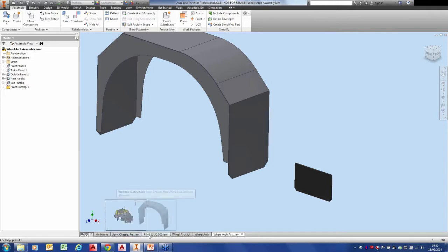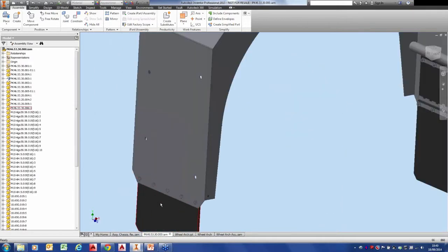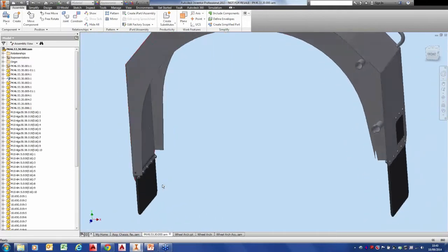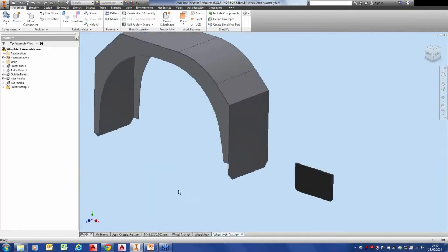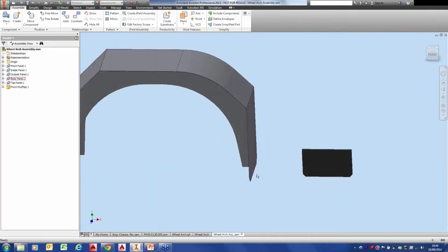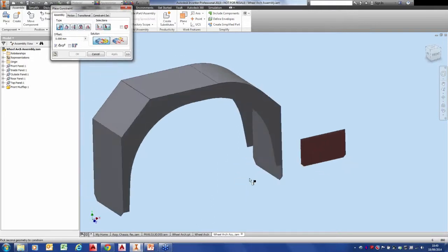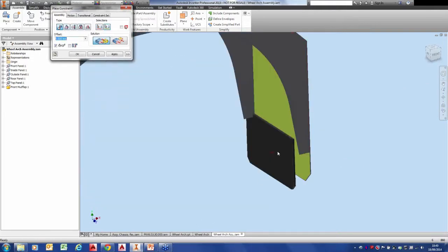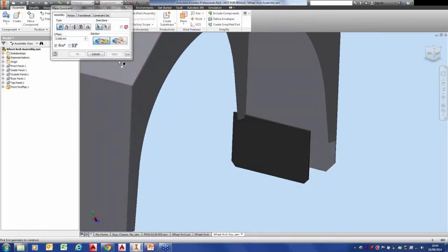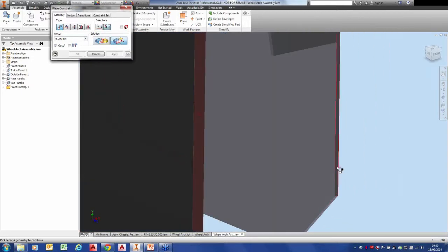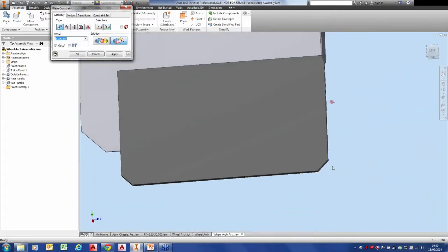So looking back at our assembly here, we've got our wheel arch. So I'm going to position the wheel arch on this face here and put some fixings in. We're doing a slightly simplified version. So I'm going to put the wheel arch on using my constraints up here. So this is our constraints dialog box. I'm going to say this face here, constrain to that face, and it pops around. And I can apply that. I can then say edge, I want to be flush. That edge is flush to that edge, and it pops in place.